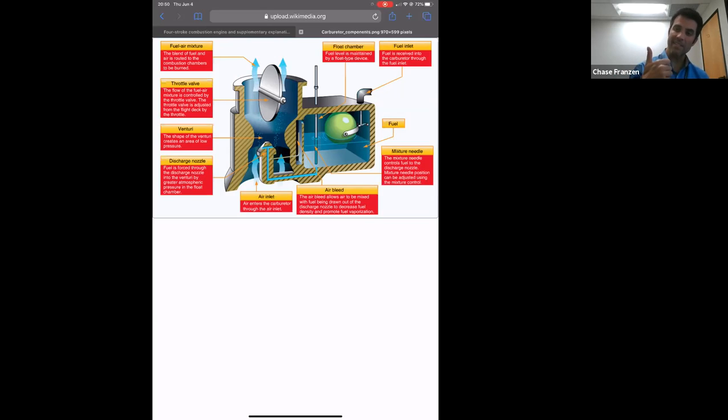So making sure we've got enough gas, making sure it's the right kind of gas, making sure the gas is not contaminated, and arguably most importantly, ensuring that you understand the nature of the fuel system. We haven't covered everything here, but a carbureted system is susceptible to carb ice. If you have a rough running engine, like 172 Romeo Whiskey did 2 months ago and declared an emergency, you've got to pull that carb heat on. It's also important to realize that you've got the 4-tank selector and you should be on both, unless you have some sort of engine issues, and then it would be wise to troubleshoot by going to one or the other. It's important to understand the fuel system because this is ultimately what allows your plane to have power and allow the propeller to spin and not be a glider.